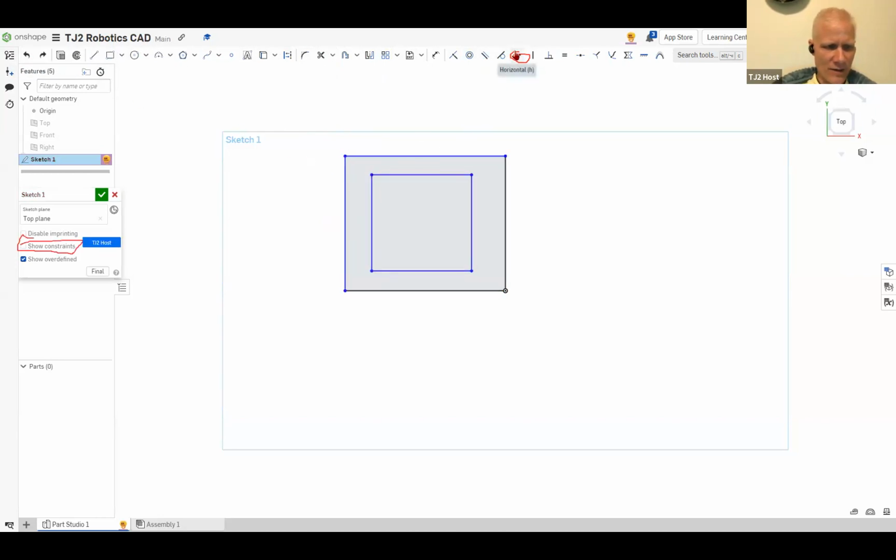If you want to see, you can actually turn on this sketch is pretty simple. So if you go over here, you can show constraints. Right. So now it's telling you what it assumes everything is. So this guy's horizontal, that's vertical. The problem is, I think this guy. Oh, can you highlight this little guy here for a second? Okay, so I think you're going to be fine because these two are parallel to each other, and they're 90 degrees to this one.